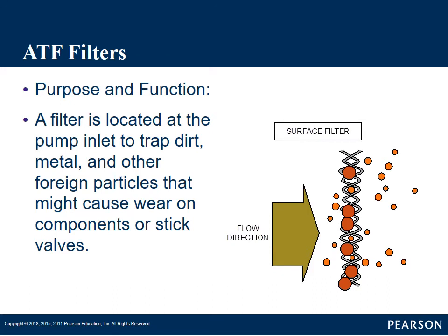Now that we're done talking about fluid itself, we're going to talk about filters. There's not a whole lot we need to go into here. The basic purpose and function of a filter is to filter out contamination, okay? Whether it's dirt, metal or foreign particles, anything that could get into the transmission, cause valves to stick, or cause bushings or bearings to wear out or become damaged, we want to try and filter those out, okay?